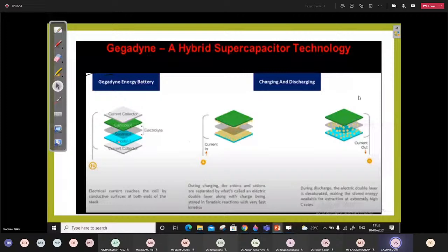So we have the limitations of the passive hybrid: the UC voltage and load voltage both float with the battery terminal voltage. This does not allow utilization of the full power capacity of the supercapacitor, and that's why we cannot select the upper limit of UC voltage randomly.